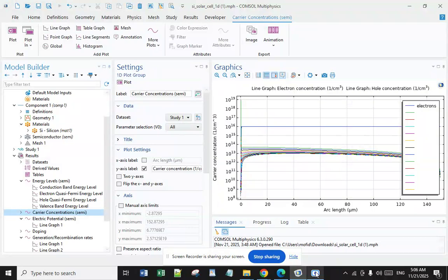A p-n junction is the boundary formed by joining a p-type semiconductor with an excess of holes or positive charge carriers and an n-type semiconductor with an excess of electrons or negative charge carriers. This junction forms a depletion region due to the diffusion of charge carriers across the boundary, and it is the fundamental component of many electronic devices such as diodes, LEDs, and solar cells.